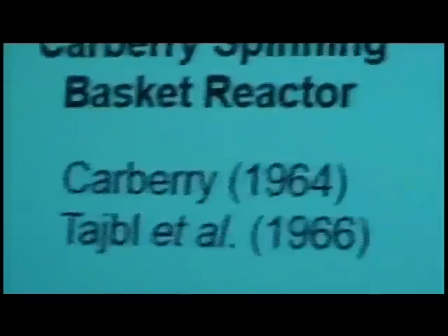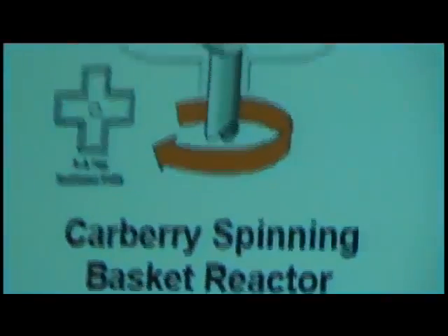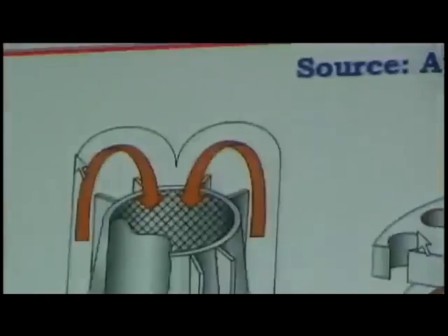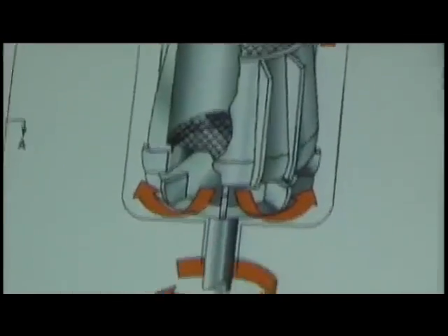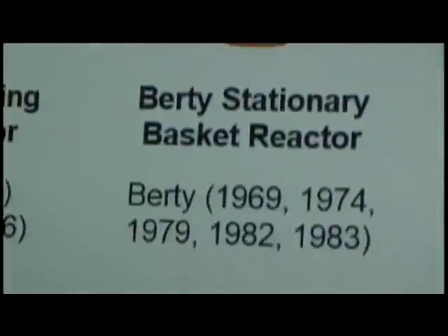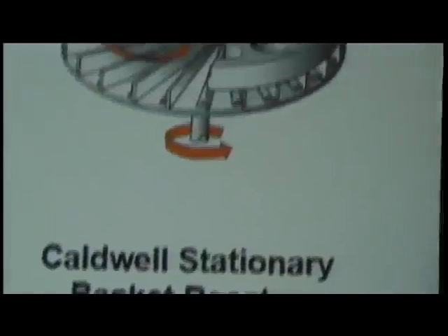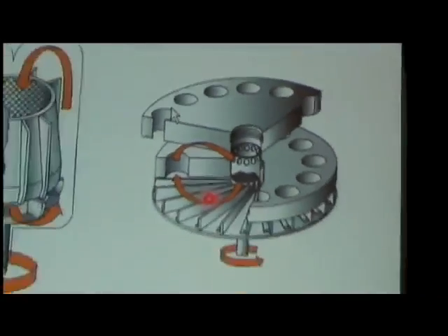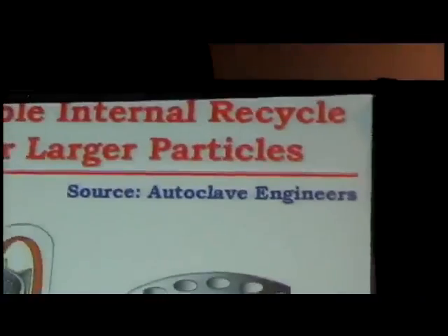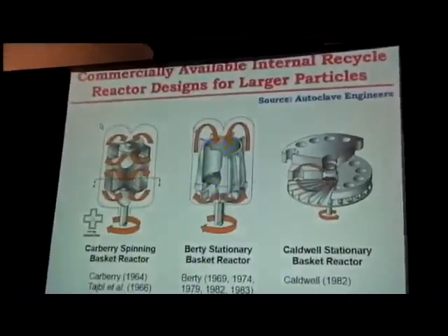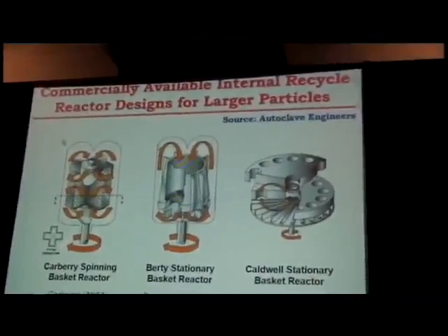This shows some of the commercially available internally recycled reactor designs, which one can purchase from Autoclave Engineers. Parr has a design, and these are based upon the classical Carberry spinning basket reactor. This is the Berty reactor, the classical Berty reactor, or of course the Caldwell type of reactor. Those are still available, and they're used quite a bit to study reaction kinetics for commercial shapes.